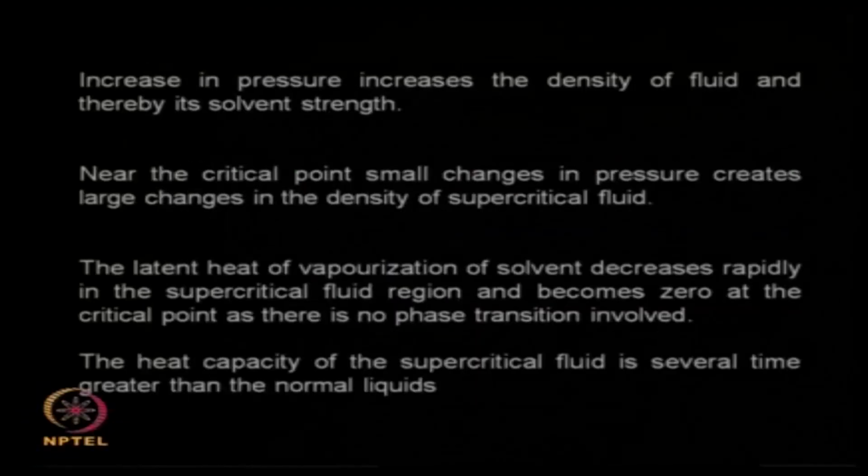So if I have a solid natural product and I want to extract the flavor or fragrance from that, then it can penetrate through small pores and then extract the flavor or fragrance. And also because it has got a low viscosity, the flow properties are also extremely good when compared to a normal liquid. Increase in pressure increases the density of the fluid and thereby the solvent strength also. Especially near the supercritical point, that is called the critical point, even when you change the pressure a little bit, you see large changes in the density of the supercritical fluid.